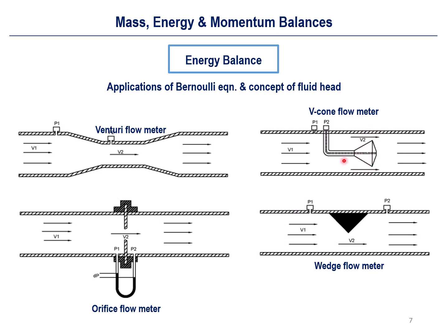But we can also apply similar principles measuring these pressure differences. And there's the orifice flow meter, where we have some contraction given by these small areas, and you can measure P1 and P2, and by measuring these pressure differences, you can measure this quantity, or some volumetric flow rate of this fluid.